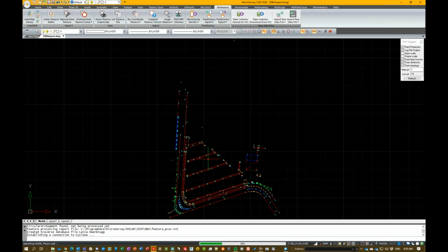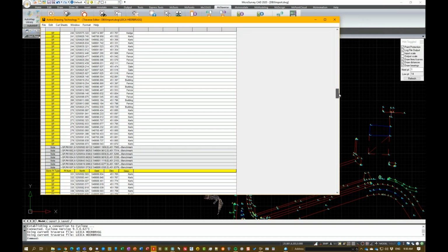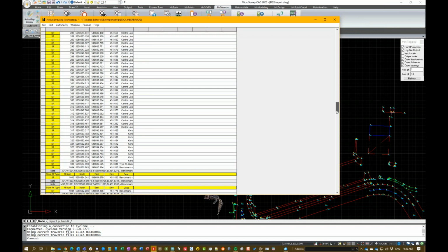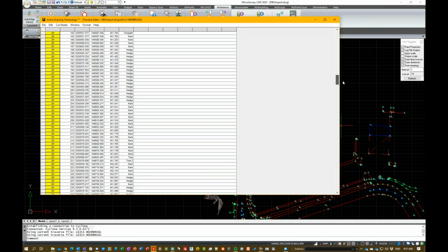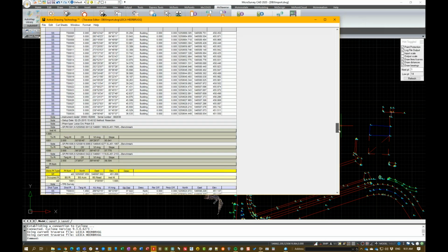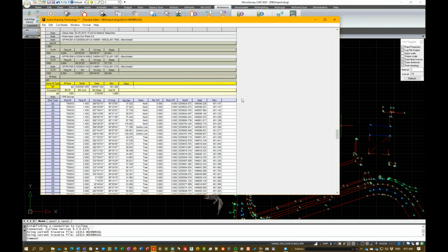You can see on my screen here, though, the blue dotted line down the center line of the road. That's the one that I set up in there. Here we have the Traverse editor, as I had mentioned. This was done by the Swiss, so they spell curb funny. But this is what that looks like in here. We've got all of our total station shots in there. The other ones up here, that's the GPS shots. Got a resection there.